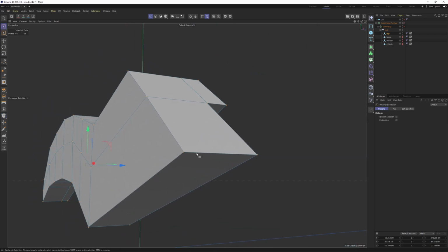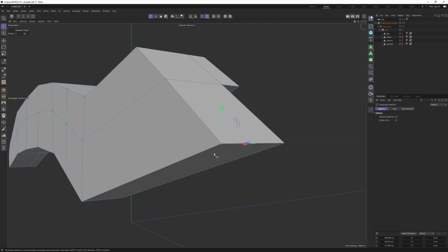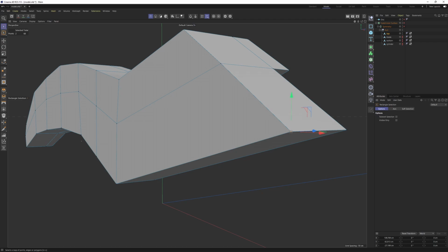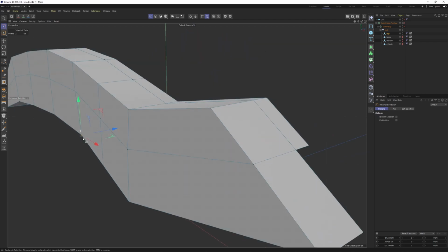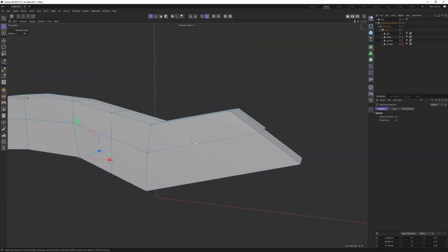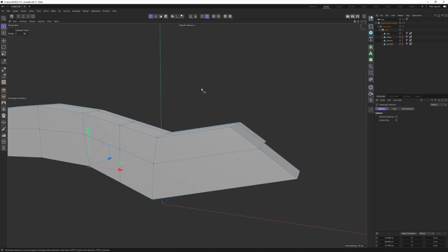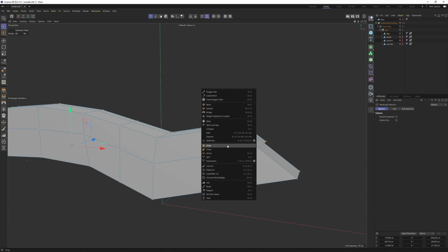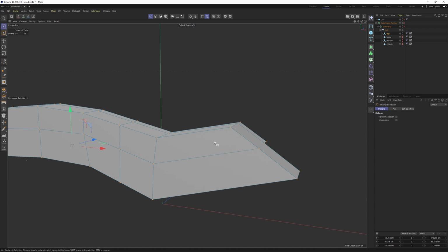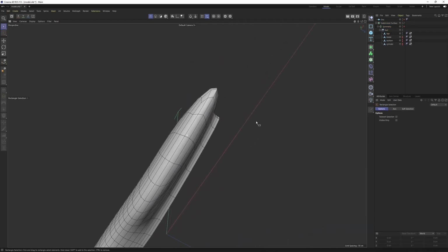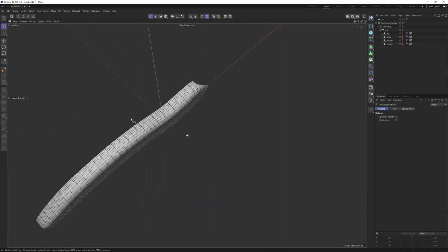I will select all the points because it looks like we have a bunch of duplicate points. Like if I select here, it says 2, like here, same. So instead of merging them with the weld tool, why don't we select them all and optimize them? Check here, the number should drop down. Yes, 58. So if I press Q, now everything looks perfect. No imperfections.